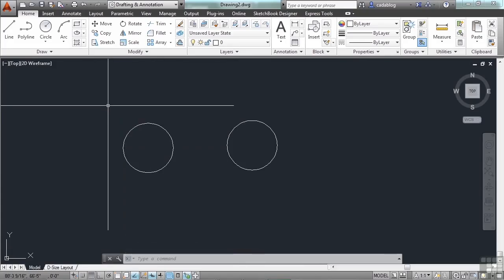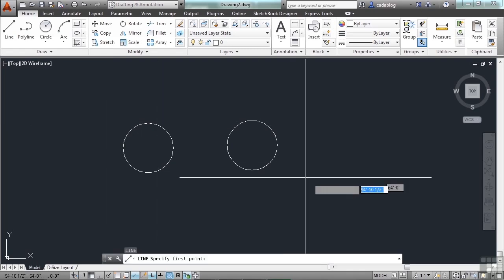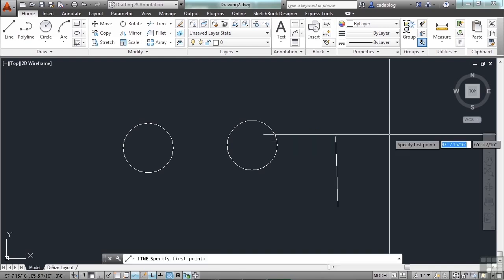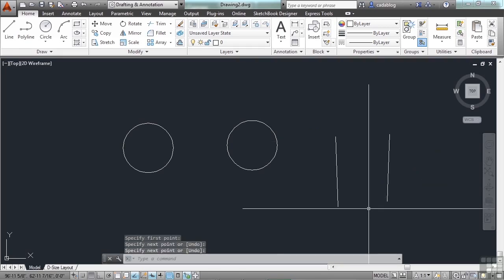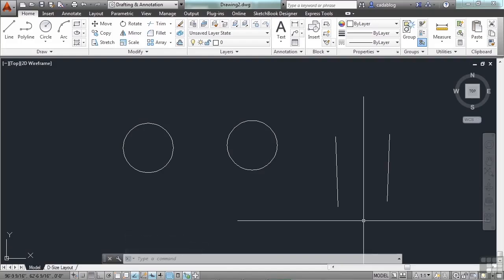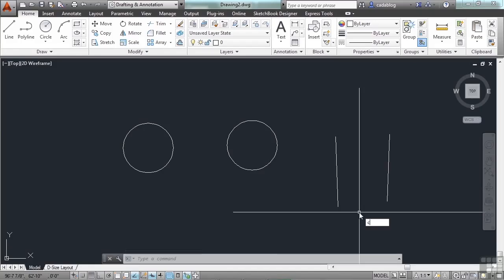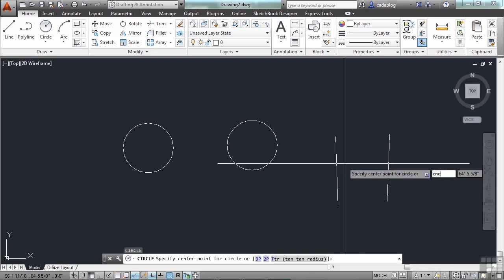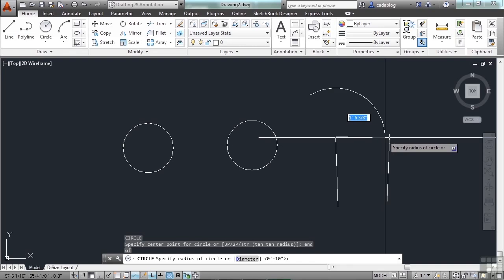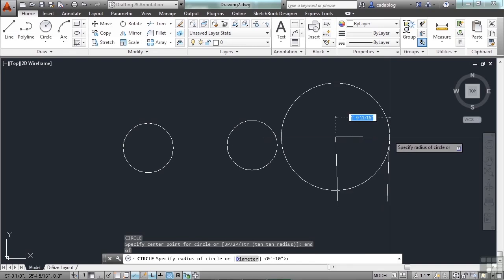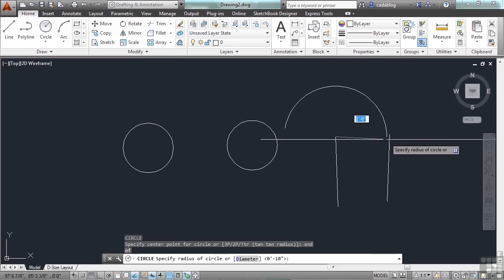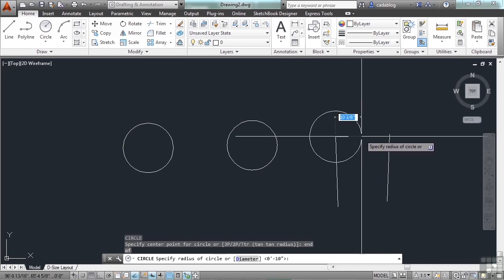That's important to know, because sometimes you have the diameter, and sometimes you have the radius. So, well, if I have one, I know what the other is. That's true, number-wise, but oftentimes when you're drawing in AutoCAD, for example, if I have this line, and I need to draw a circle, what do I have? Do I have a radius or do I have a diameter? Well, that depends. If I start circle and I draw from this endpoint and I want to draw to this endpoint, I have a radius, not a diameter. That's true. But if I want the circle to come to the middle of these two lines, I will need the diameter. I'll show you the difference.